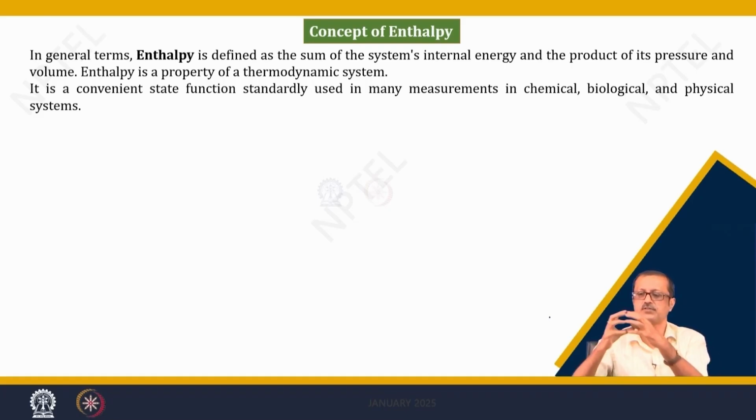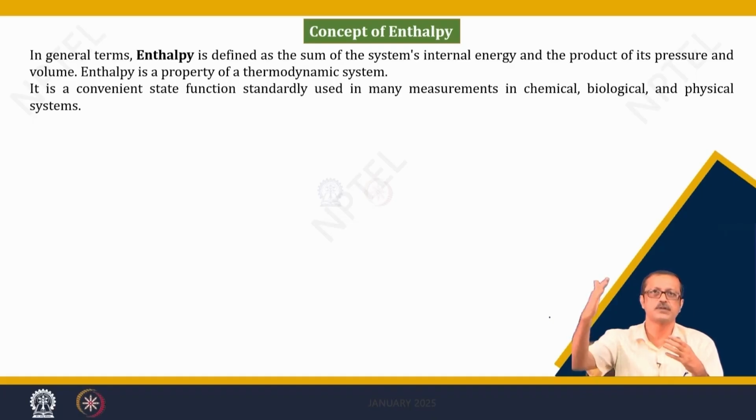Suppose there is a moisture change also, so there is either latent heat in or latent heat out, depending upon your relative humidity changes. That gives a new total energy state E2. The difference between E1 and E2 is the enthalpy difference between these two coordinates of the air.